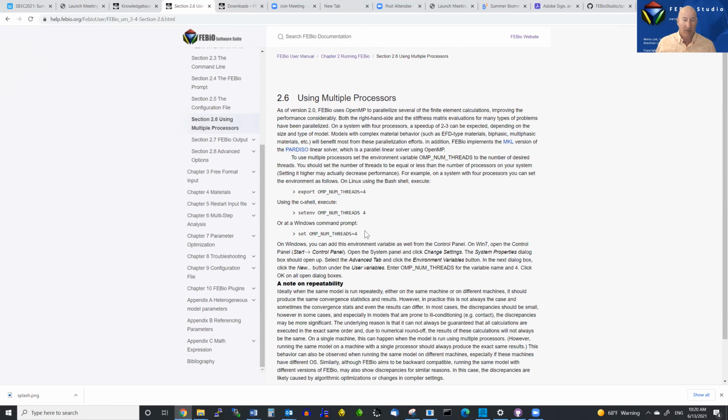You want to simulate compressing this piece of bone to figure out effective properties. In this case, you have no contact and a single material type with various modulus values. That results in a stiffness matrix that's very well conditioned but quite large, because those problems commonly have millions of elements. That's the type of thing that works really well with iterative solvers.